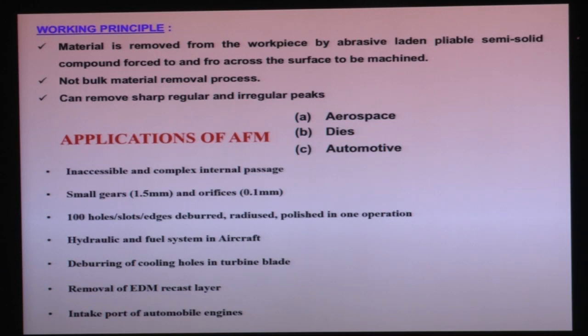So these turbine blades have burrs generated after machining, and that deburring operation after machining can be done by this abrasive flow finishing process. Removal of EDM recast layer we have already discussed. Another application is the intake port of automobile engines. If there are some burrs or any irregularities, they can be polished by the abrasive flow finishing process.